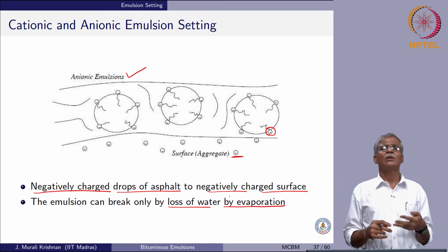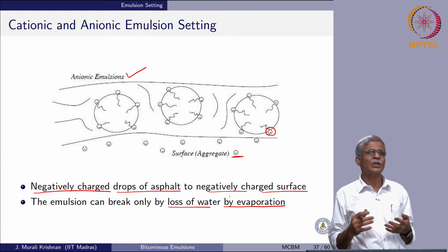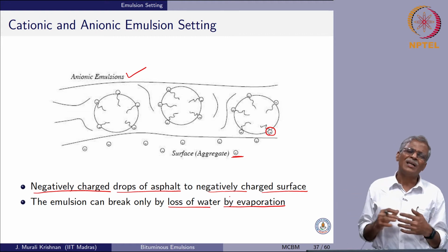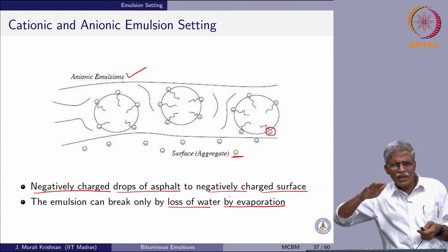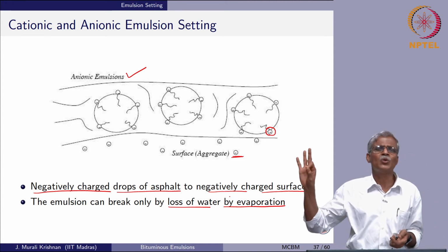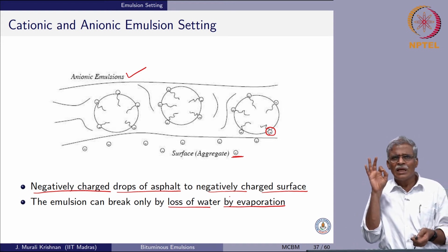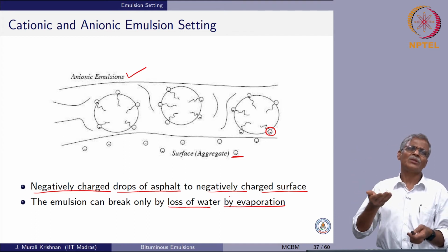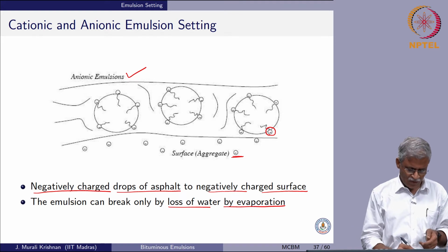Let us say you are trying to do this kind of cold mix in a very, very hot place, then the emulsion breaking can be sufficiently rapid, and that is something that you also do not want. So, you are looking at breaking the emulsion in the manner in which you want, and you also want to monitor the strength increase; the rate at which the strength increases should also happen in a very specific way.